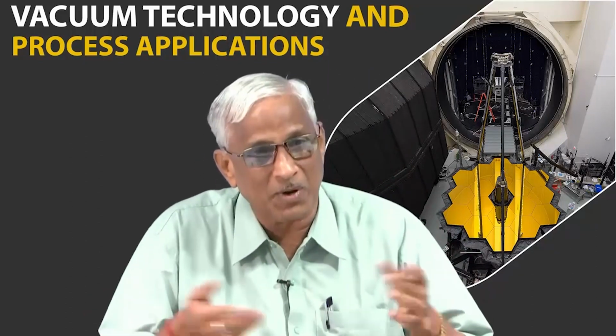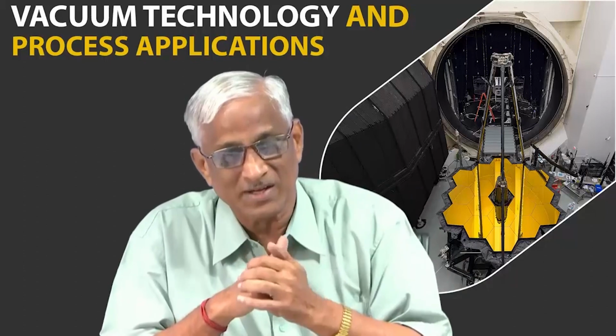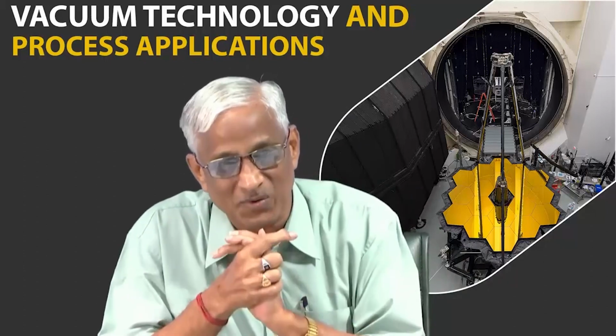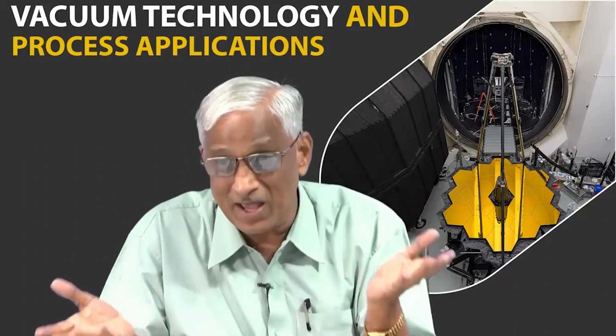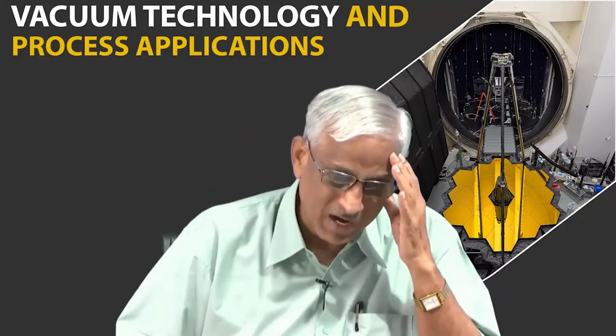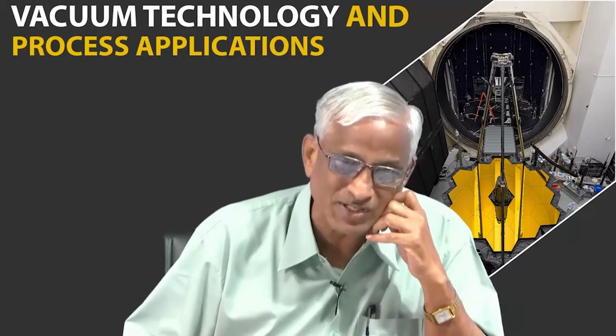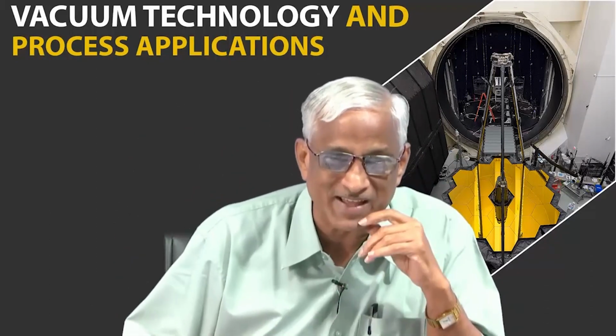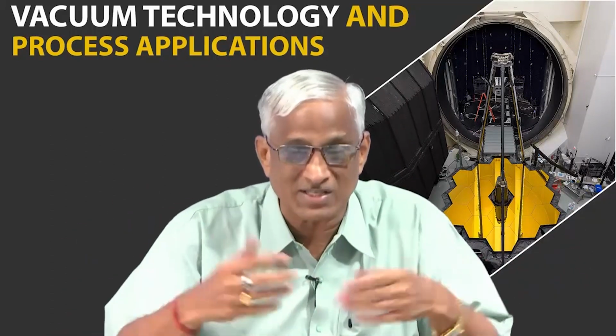Okay. So, if you are not getting proper vacuum on the high vacuum side, then it is not moisture alone, and you need some helping hands to understand the problem. So, they are leak detectors or RGAs, etc. From there you will get a spectrum of impurities, and with your experience of what materials have been introduced inside, you will know whether outgassing is there or not. Bake the system a little, and if the vacuum improves, then outgassing is the cause.